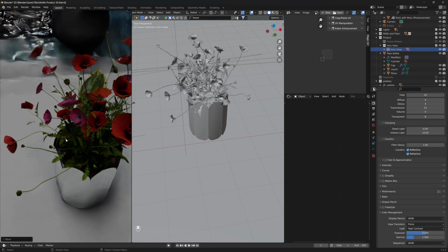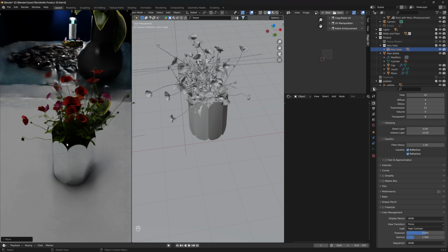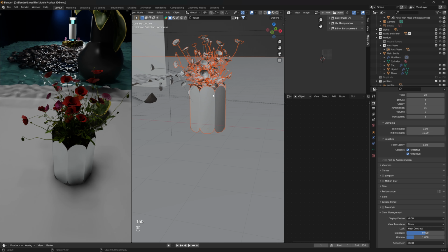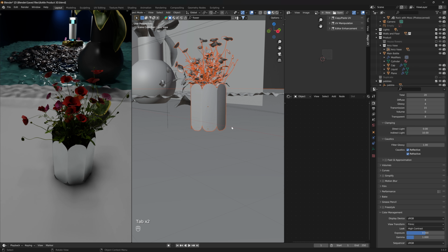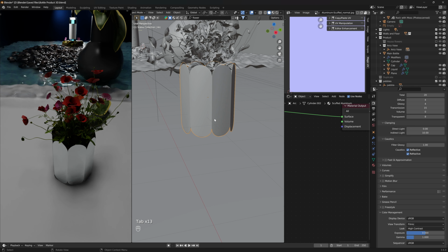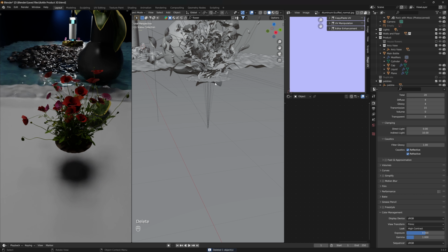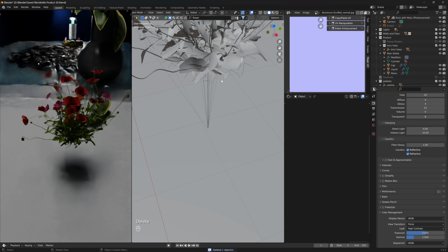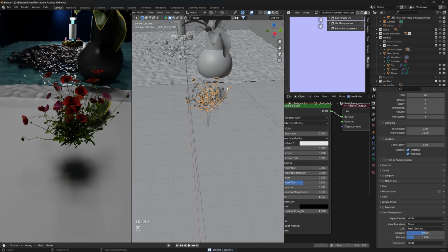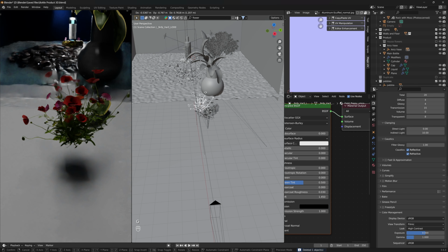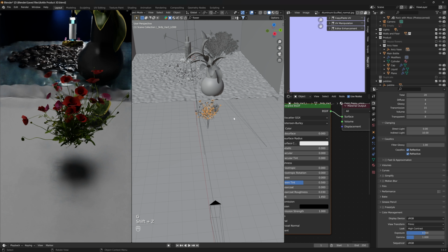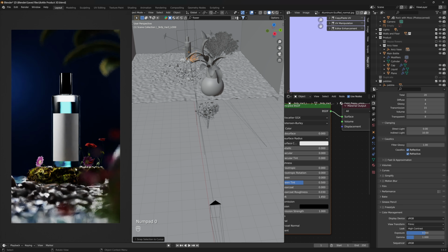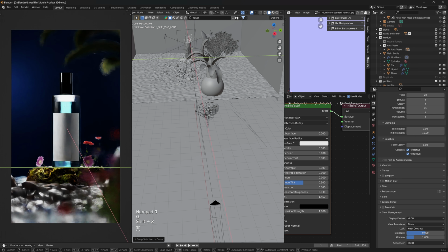Yeah, these flowers are looking real nice. All of it is looking real nice, to be honest. We just need to, I'll go in edit mode. I'll just delete this. Okay, also this, then select it, then G Shift Z, or instead Shift S, selection to cursor, hit 0 to see how it's looking.